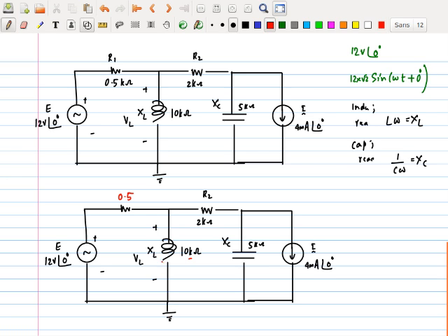Then here, this is an inductor. So I take this out, and I write J times 10. Remember, if it was an inductor, it was J L omega, was the actual impedance, right? Actual impedance, right? This part of it is called reactance. Then if I put in the J to indicate that it is actually 90 degrees offset, then you call it the impedance.